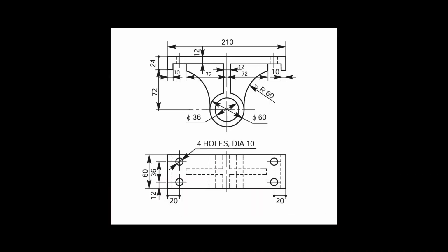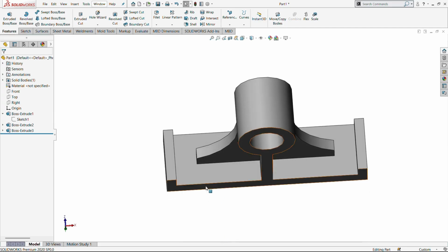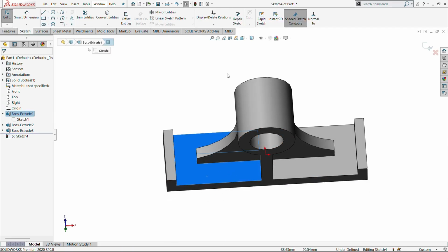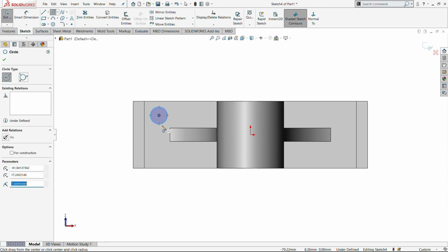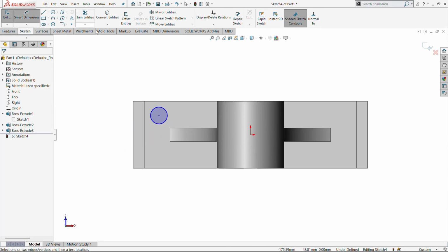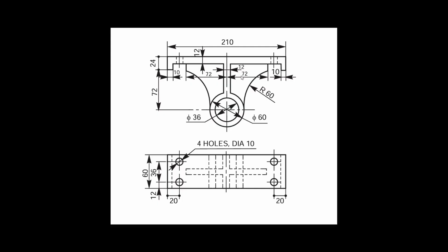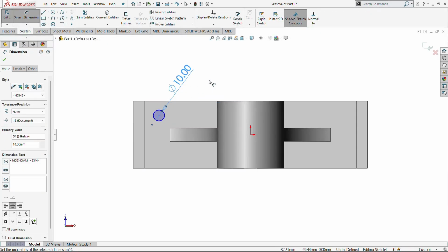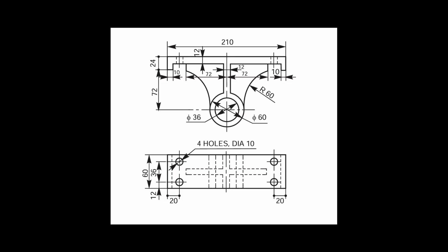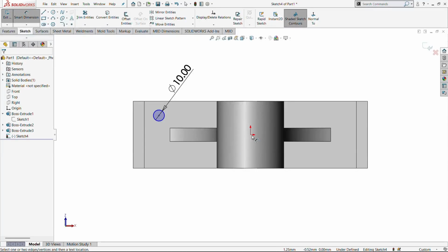The only thing we need to do is create a pocket on 4 different corner points. Now select one of its faces, either the flat bottom face or the top one. Once we select it, create a new sketch and draw a simple circular profile at the particular position. Then use the dimensions to fix it, both the diameter as well as the position. What are the dimensions of it? 4 holes have the equal diameter of 10 mm. So mention 10 mm.